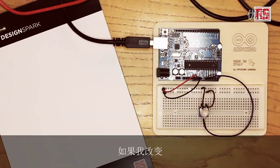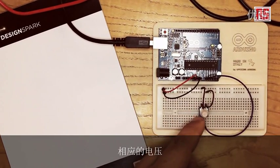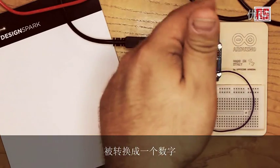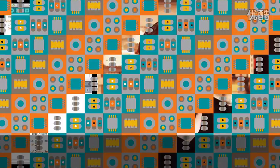And then we have a red and black wire going from those two rails to the 5-volt and ground signals on the board. So when I change the position of the potentiometer, a corresponding voltage is coming out of this wire and going into the analog input 0, and that data gets converted into a number that gets sent down the USB cable over to the computer and then to the Processing code.